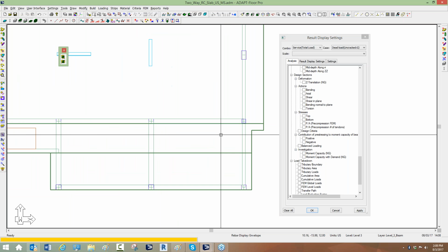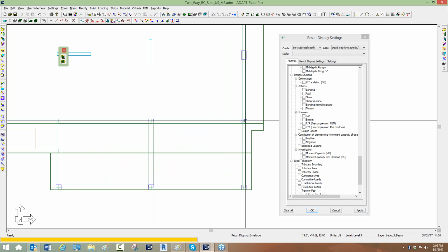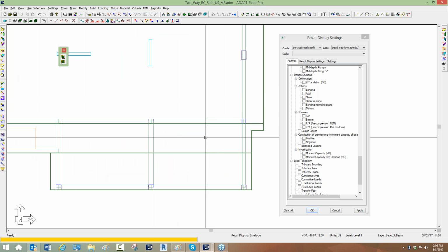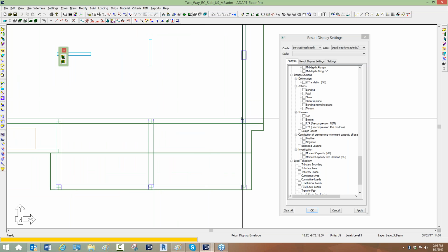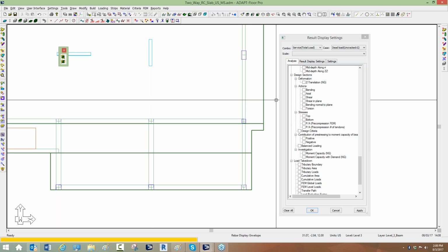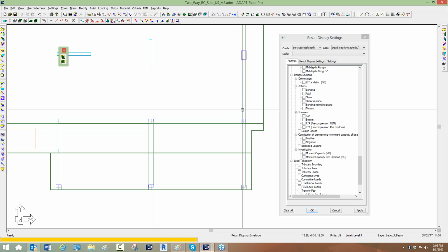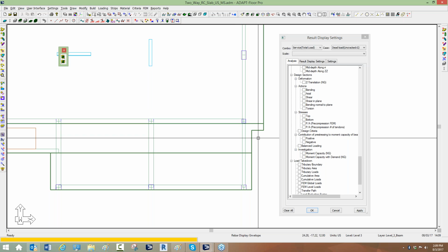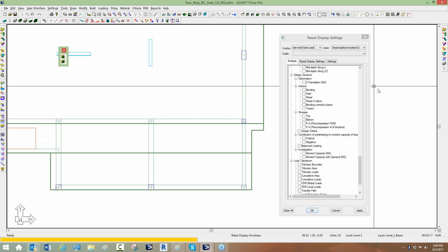Note, however, that even though I release the beam bending, the section cut still has slab associated with it. So if you're expecting to see a zero moment at the end, you would see zero moment if you look at only the beam bending diagram, but because the design cut includes both beam and slab, you're still going to have some bending at that location, probably negative bending.